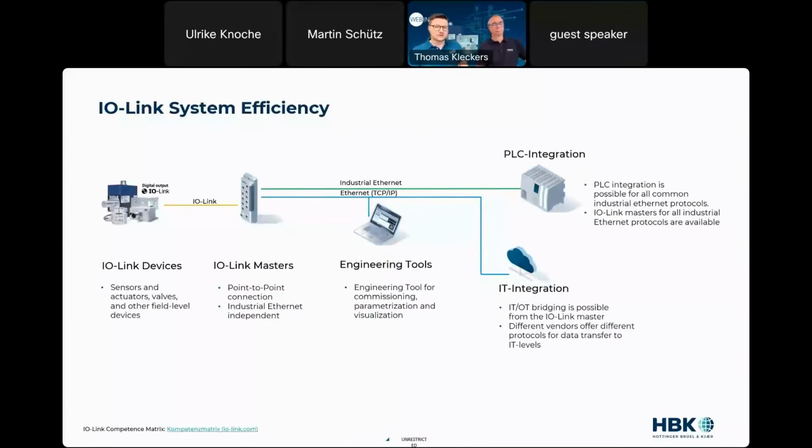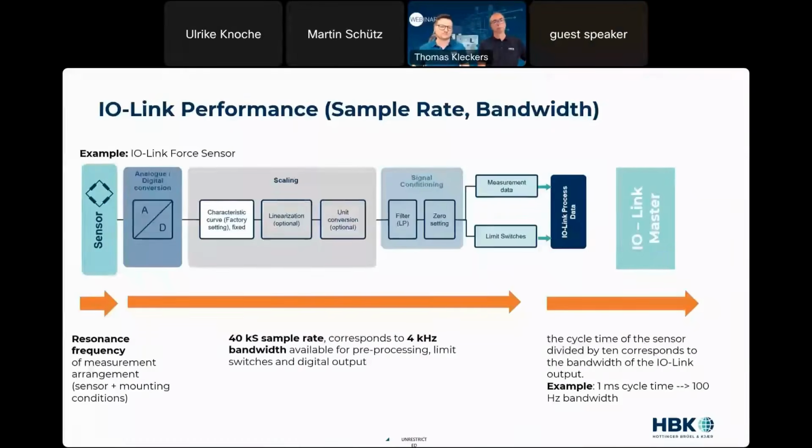Yes, and here maybe another representation of the typical IO-Link system setup. On the left side, you see the IO-Link devices, which would be the equivalent to our IO-Link sensors. We have the master, and the point-to-point connection between the devices and the master. What we are going to showcase today in our demo setup in a couple of minutes is that we are using the Ethernet connection from the IO-Link master, and we are using engineering tools, or we are logging into the web server of the IO-Link master. Typically in applications, in machines, in the automation, what you would do is you have the industrial Ethernet connection going to the PLC.